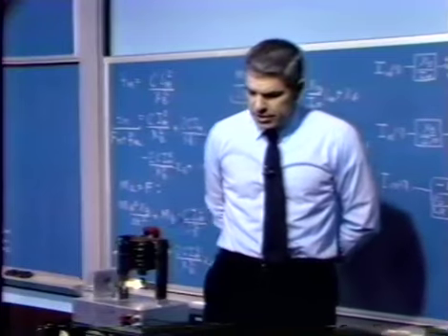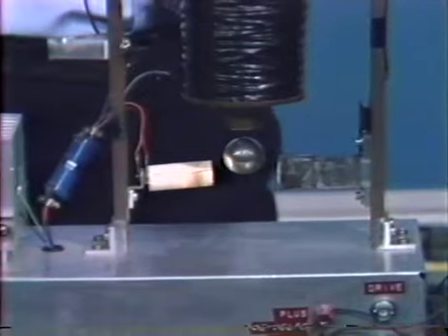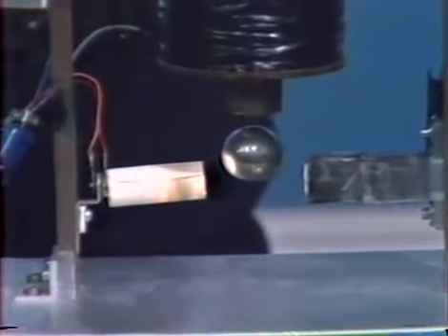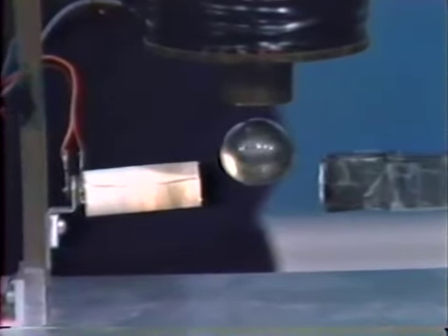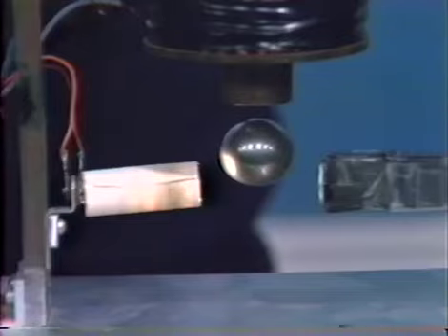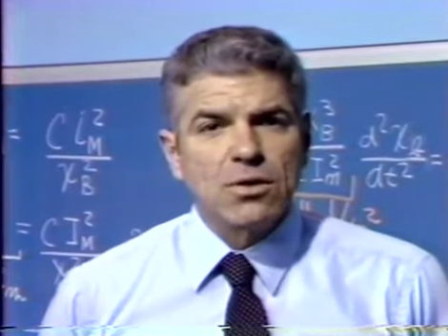What I actually did when I put together this system was to go through an analysis very much like I've done here and convince myself that I understood how things worked. And then I went ahead and built the system, with provision to adjust the two critical parameters, in particular to adjust the gain of the amplifier, the quantity A naught, and also adjust the location of the zero.